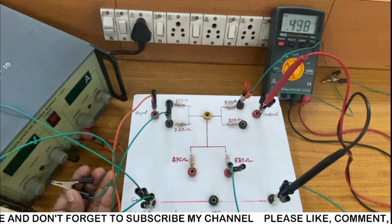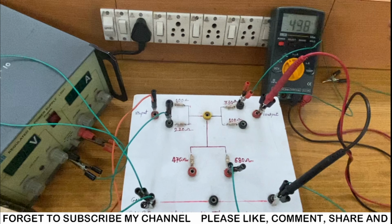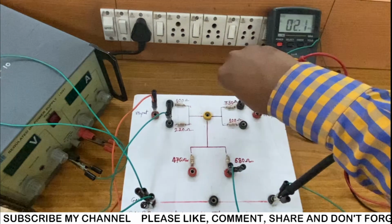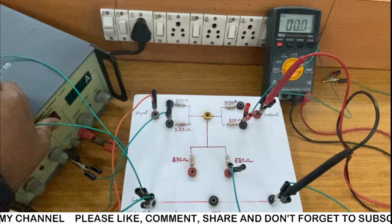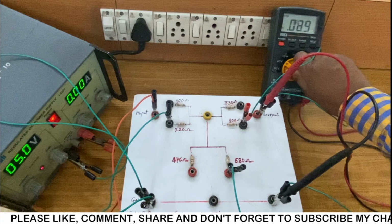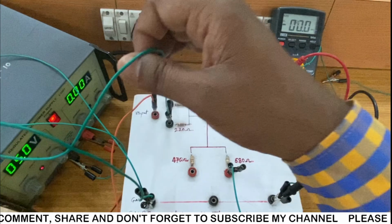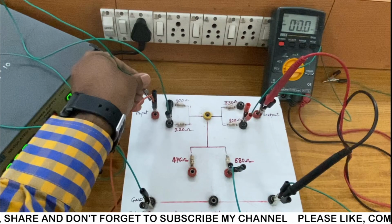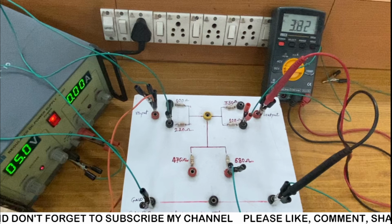So we can do it again for the next two iterations. So I'm going to make the supply on. For that purpose we need to change to the next combination. I'm going to make R2 as 100 ohm. We need to put it into DC, and we need to connect the resistance to 22 again on the input side. So we are measuring VTH, so it should not be shorted. So it is 3.82 volt.